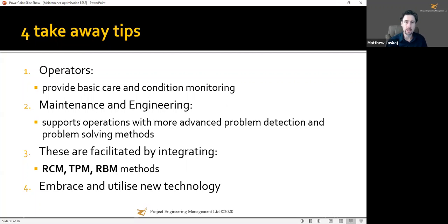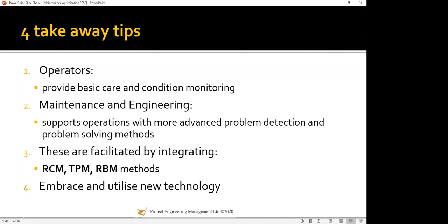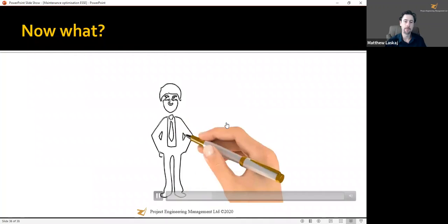20 years ago, when we were doing these studies in a packing plant, I would have to go and stick a disc on the side of a motor, get a vibration probe, stick it on the side of the motor once a month, have a little pack of computer next to me where it uploaded in, go back to my office, upload it to my computer, make a graph out of it, look at the graph from last month, compare it to this graph from this month. It took so much time. Now, with the Internet of Things, we can stick a remote sensor out onto an oil rig, send our information back, and artificial intelligence or a digital twin can help us predict when that failure is. So our predictive maintenance is so much more accessible and so much better.